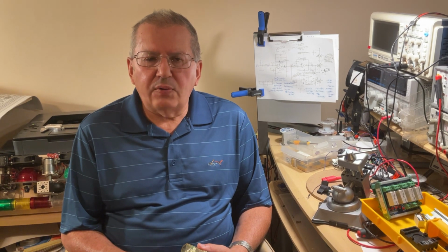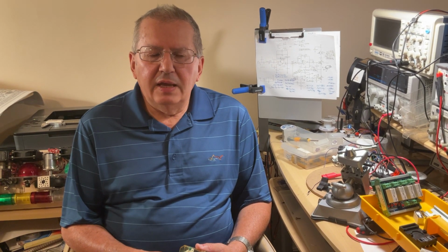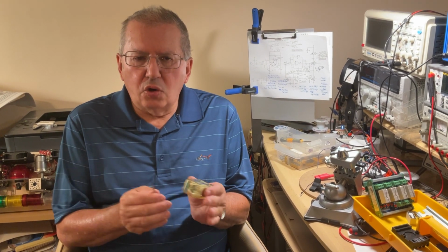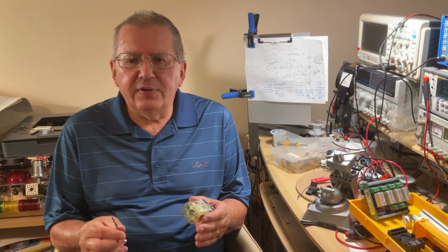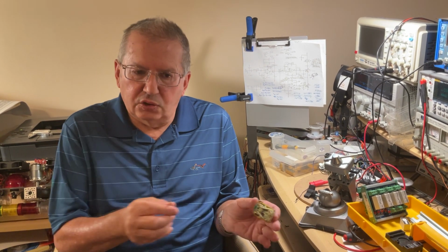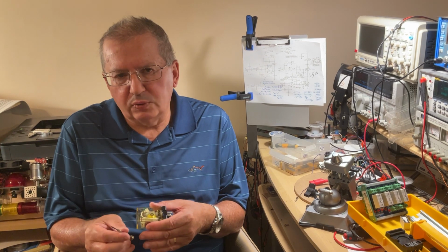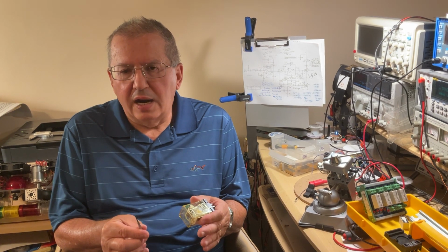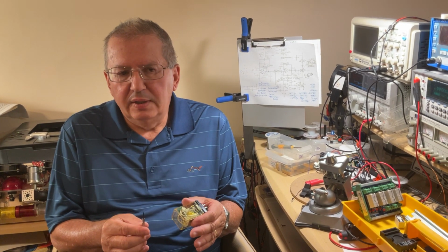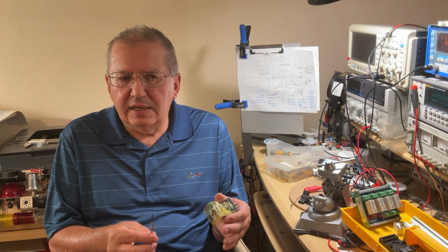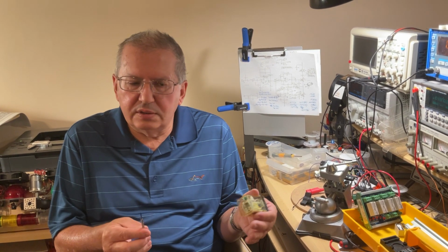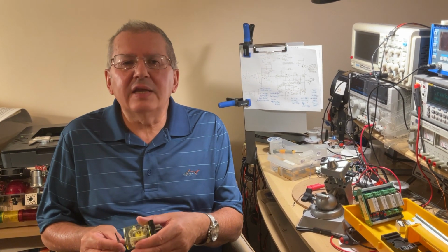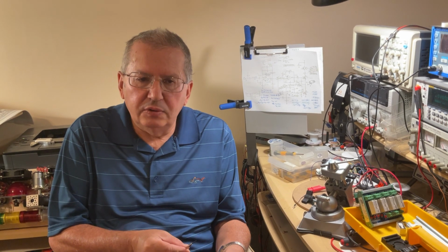but the standard or the traditional electromagnetic relay has a very interesting property. Being made of two things, coil and contacts, that's a perfect insulation between the two parts, the control, which is the coil, and the output, which is made of contacts. So because the two parts of the relay are electrically insulated from each other, you can energize the coil of the relay in DC, which is the most common way to use it. But the contacts at the output of the relay can be used either to drive a DC load or an AC load.